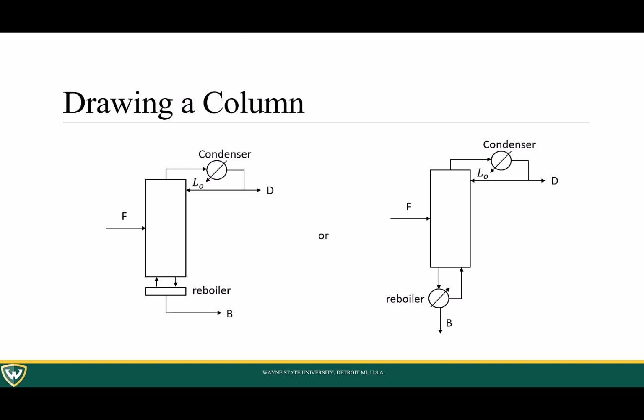Also, you would want to make sure you write out your Z. If you have Z1 is equal to whatever, Z2 is equal to whatever, and so forth. Same thing with, now these are no longer Y's. These are D's or X's, because this is liquid because of the condenser. So because this is liquid, you would have XD, and here you would have XB. Okay.